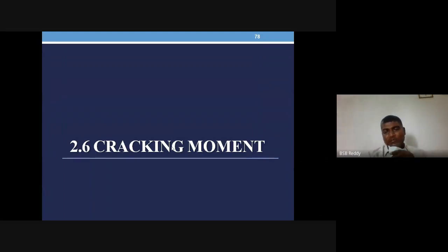That is possible by having a kink in the cable profile wherever there is a point load. The sudden change of angle should be there in the cable profile. That is what we call a kink.